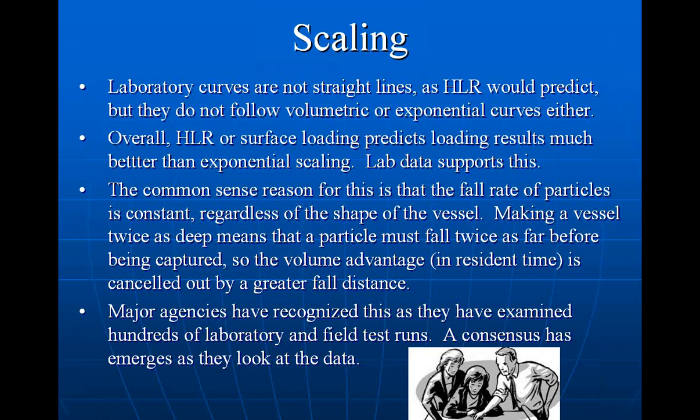And there's some debate. I would not be honest and fair with you if I didn't say there's debate. The common sense reason for this: if you take the same device, a 4-foot round device that is 8 feet deep, and then you make it 16 feet deep, a volumetric scaling guy will tell you that you've at least doubled the capacity because of the math. The fall rate of particles is constant, so making a device twice as deep means the particle has to fall twice as far. So the volume advantage in residence time, the water would obviously stand there twice as long, is canceled out by the greater fall distance.